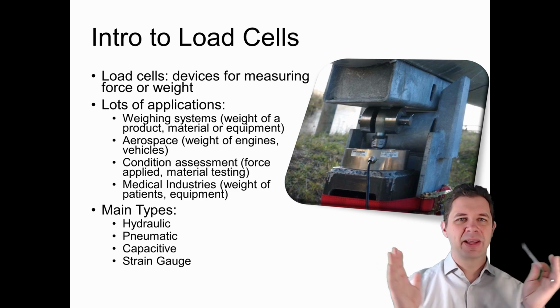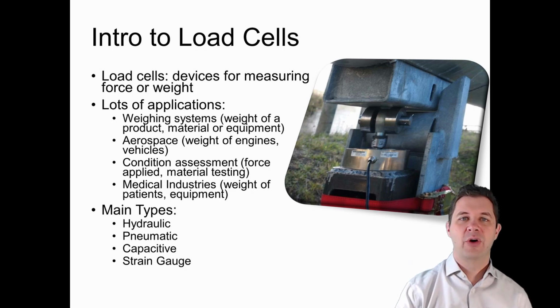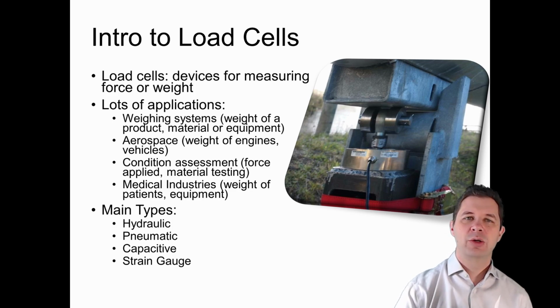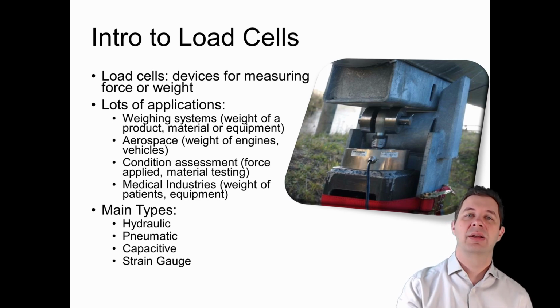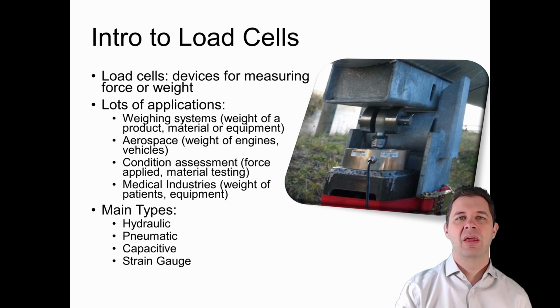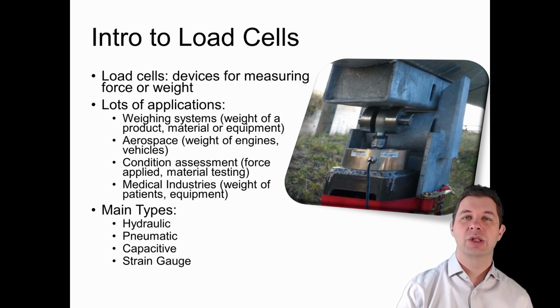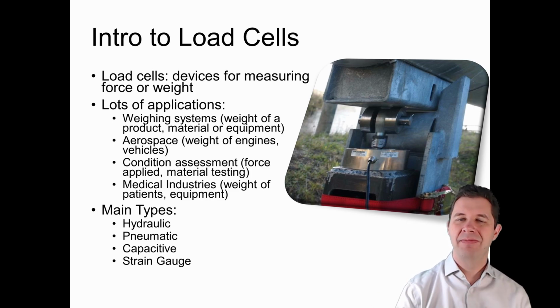And there's lots of applications that we use load cells in, from weighing the weight of a car or weighing the weight of an engine block within a car or an aircraft or something like that. We can use them for condition assessment. I've used them for condition assessment of concrete using a penetrometer, measuring how much force I can apply when I'm pushing a probe into concrete. We use them within the medical realm of measuring the weight of equipment or of patients, because the amount of drugs and the efficacy of those drugs will change based on the weight and size of the patient. And measuring the weight of things like powders, for example, when we're filling bags up with something or we're mixing something. All different areas that we use load cells, because we're wanting to measure the force or a particular weight across something.